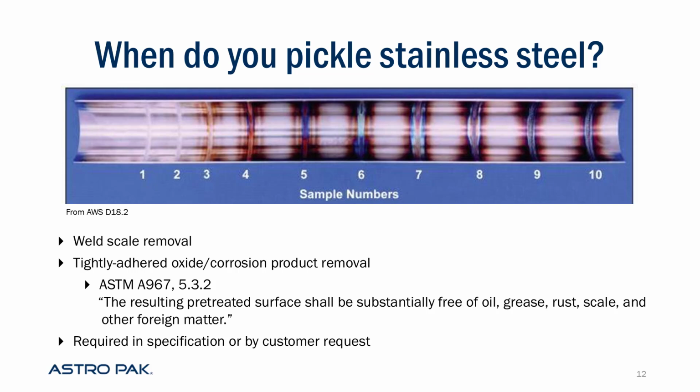It is iron rich in the oxide, a very poor chromium to iron ratio, and AstroPak typically sees an untreated weld or weld heat affected zone as one of the first spots to corrode in a system. Now, if the weld gets treated, pickling is one of the better options you can use to treat that and remove the color, but any sort of descaling works. So descaling can include media blasting or grit blasting, can include mechanical polishing, so stripping out the weld. We've seen a lot of that this week, or pickling. And there's another option for gel pickling because you don't need to send gallons of the very aggressive acid through the surface unless these welds are inaccessible for a gel application.